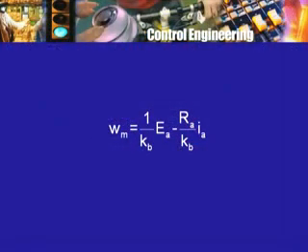So let us get back to our example, and there we had decided that the two equations that we have, let me remind you what are the two equations. One was the armature circuit equation involving the applied voltage Ea, the back EMF which was dependent on omega m, and the armature drop Ra Ia. That equation we solved for one of the two variables, either omega m or Ia, in terms of the other two, and correspondingly started constructing a signal flow graph.